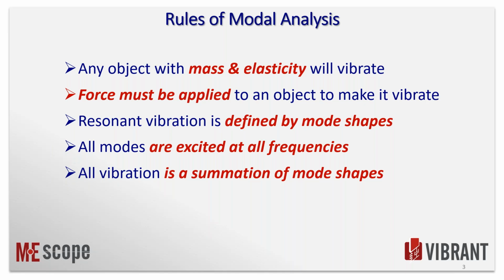So resonant vibration is defined by modes of vibration. So when people say, gee, I think I have a resonance, or even an acoustics problem, because most things behave like a speaker, they push the air around when they vibrate. So you might even hear the vibration, but it's due to resonances. All modes are excited at all frequencies. That is one of the assumptions we make when we curve fit data, broadband data, and extract modal parameters.